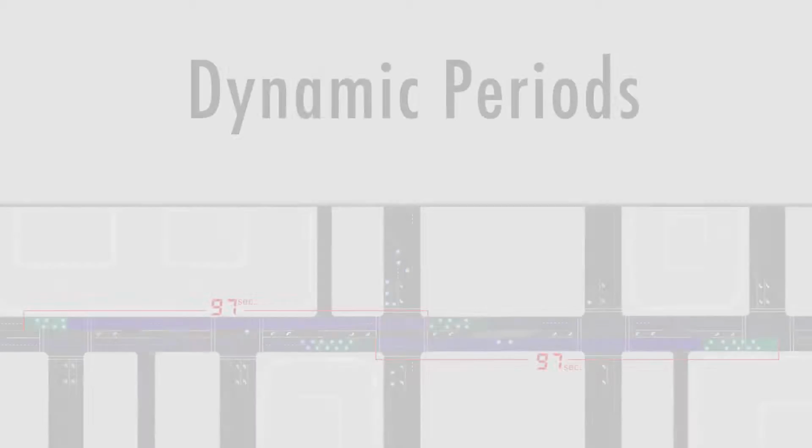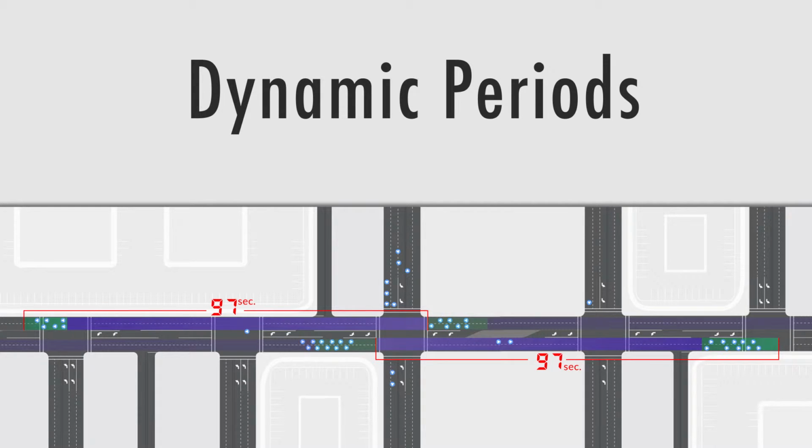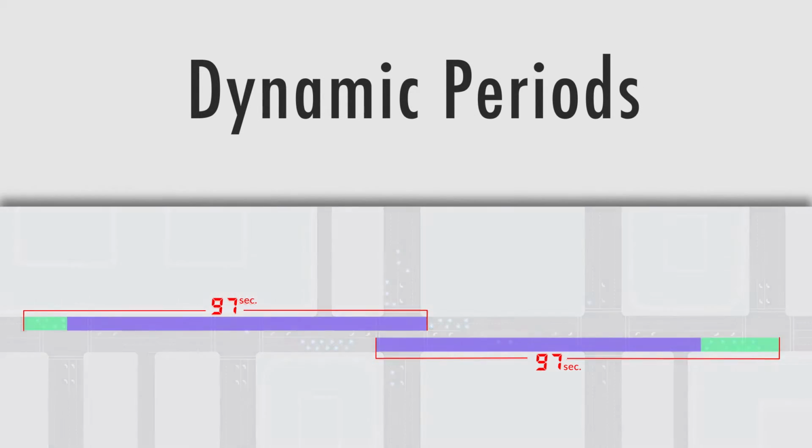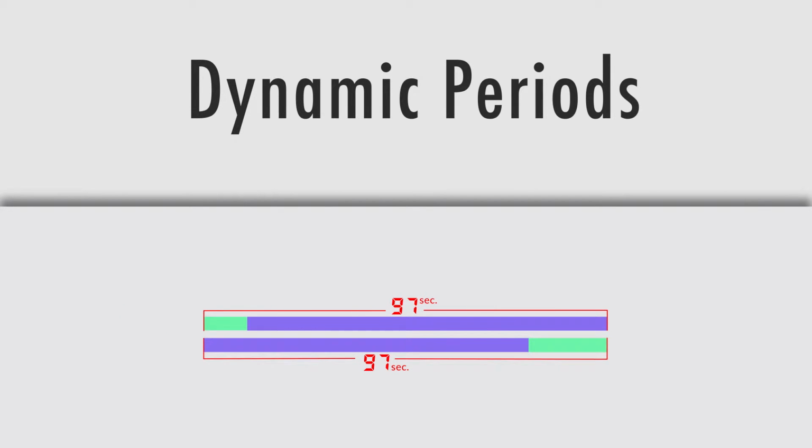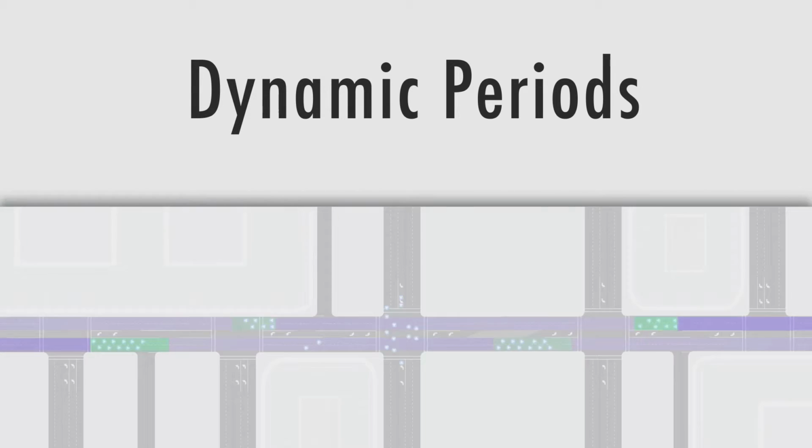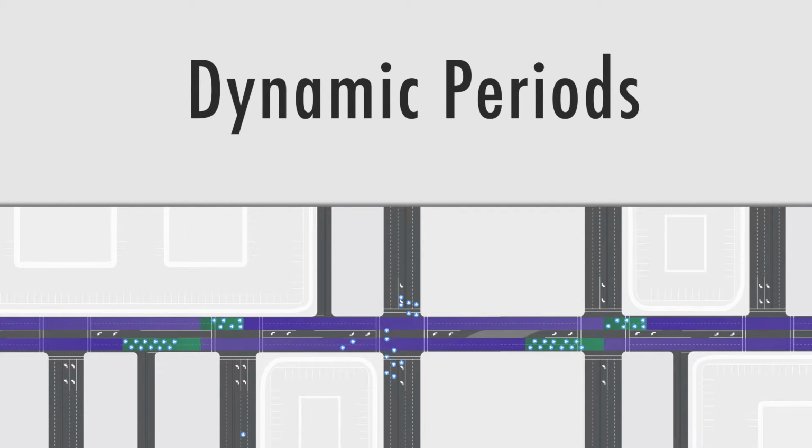Traditionally, motorists on the main line may be forced to stop due to the signal timing relationship associated with irregular spacing, causing a cross street or a left-hand turn to be served instead of maintaining bidirectional progression. InSync's period length allows bidirectional progression, and it is the same for each intersection across the network in both directions. However, the period does not have limitations like traditional fixed sequencing relationships between neighboring intersections.